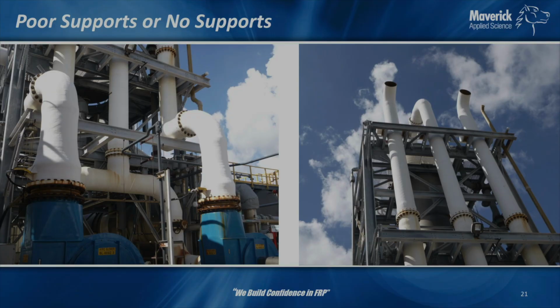Here's another example for support. So here's a couple stacks coming off of blowers. You can kind of see it come up here, pipe sitting on the steel here, and then they're going up. This is the top end of that. And so you've got kind of some guide points here. Again, guide points, there's no anchors to carry the dead weight. So all the weight of that riser, which was probably something in the order of 50 foot tall, is all resting on these points right here. Really not suited for that.